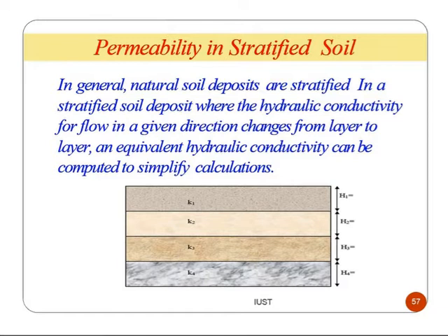Permeability in a stratified soil. In general, natural soil deposits are stratified. In a stratified soil deposit, the hydraulic conductivity for flow in a given direction changes from layer to layer, and an equivalent hydraulic conductivity can be computed to simplify calculation.